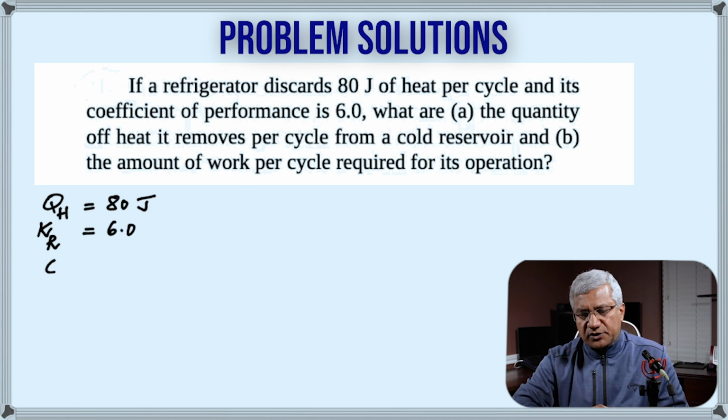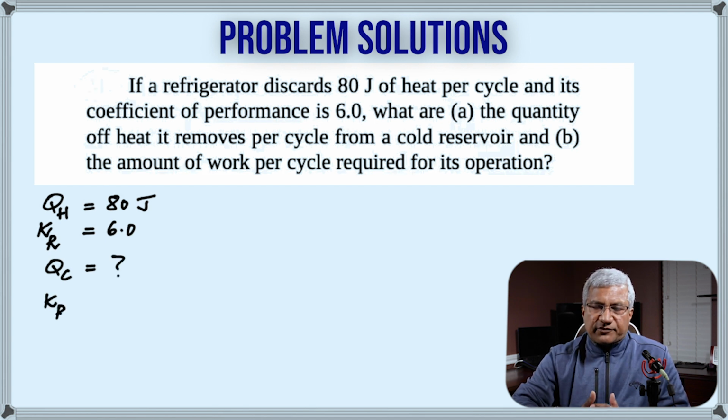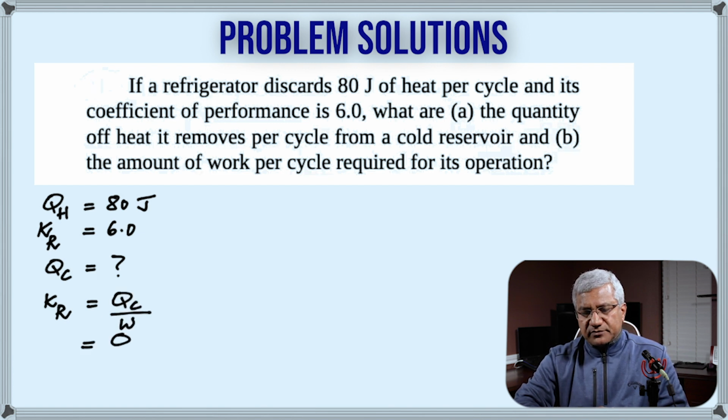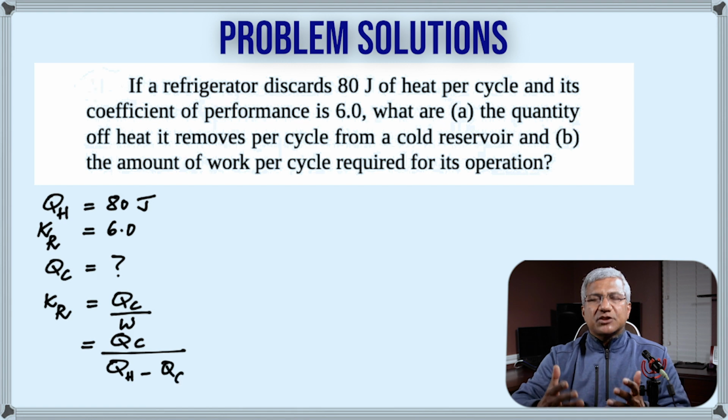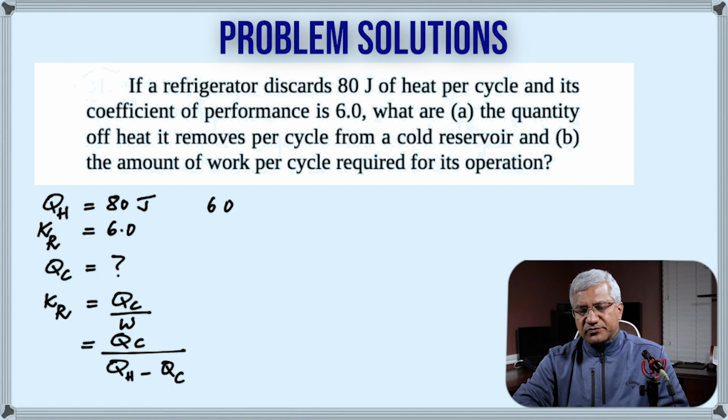And we're looking for QC. By the definition of coefficient of performance, it's QC by work. That is QC by QH minus QC, because work is QH minus QC.